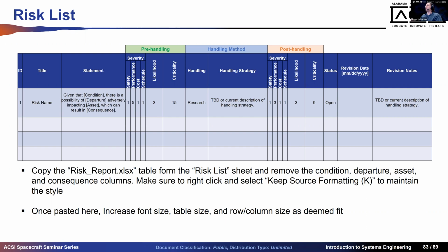That's the consequence. So we'll rate this in terms of its severity, for the safety of the personnel or the safety of the satellite. One heater loss is probably not going to take the whole spacecraft down. For performance, yeah, it's going to completely break that one part. 5, sure. For cost, I might give this more than a 1, maybe a 2, because maybe you want to put a redundant power transistor in there. And then schedule, no, this is probably not going to cause a significant problem with schedule. You can have a likelihood there. The likelihood is for any of these. The performance times likelihood will be the criticality. Fine, we'll talk about what that does in a second.